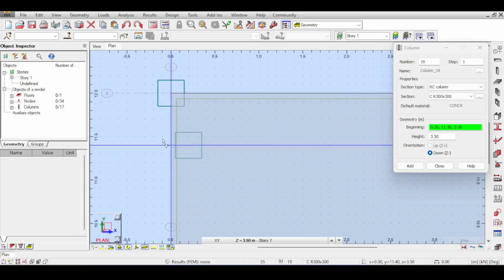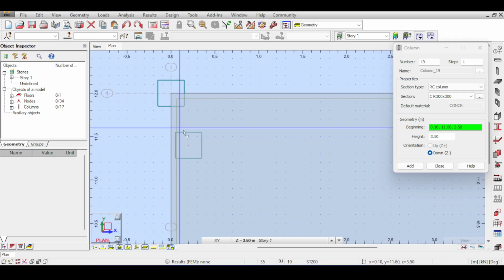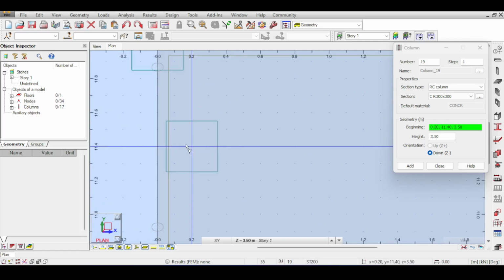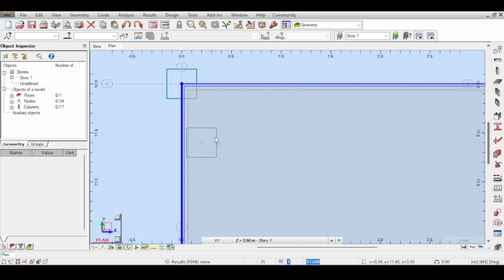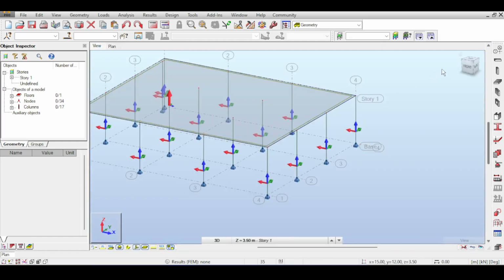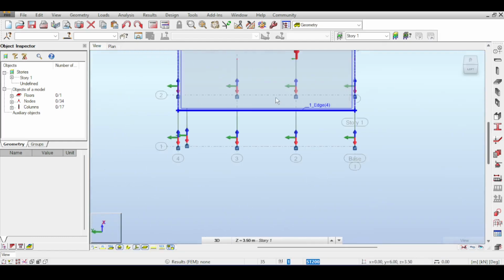You could draw the column here, which would satisfy the beauty of having a column inside the slab. However, in reality, if you do this, then the rest of the slab is considered cantilever outside, so it will be developing negative moments, which is not really the case. But those are inaccuracies we have to deal with using the finite element method, and that's the reason why factors of safety do exist.